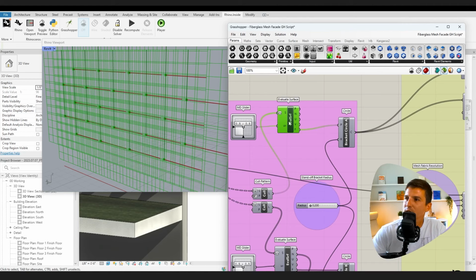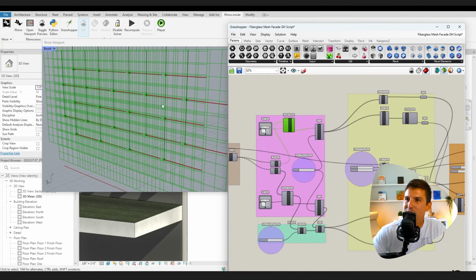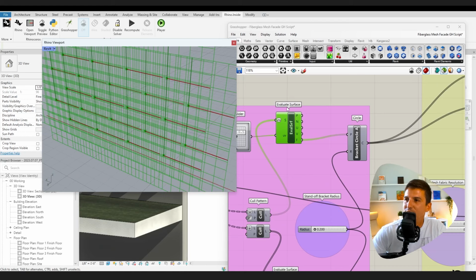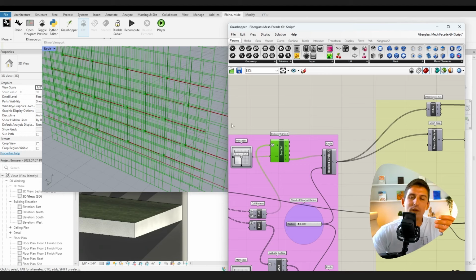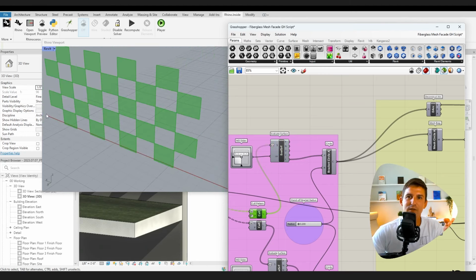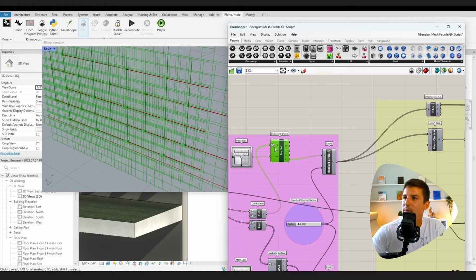So then to know where the centers of those surfaces are, and this looks crazy right now, we have to do an Evaluate Surface command and reparameterize the surface. Because right now, all of these surfaces have a relationship to each other, like to the origin, and these are all a certain distance away. When we reparameterize the surface, my understanding is we are now defining each one to have its own unique origin or its own unique value, whereas the parameters before, 0.5 might have been some distance in space, and 1 isn't the ultimate value at the end.